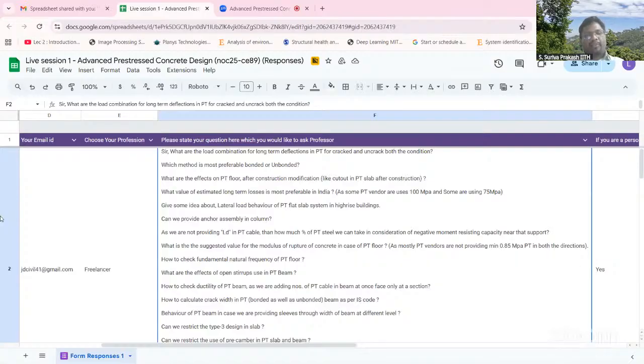So that's the reason FRP-based strengthening is typically very commonly done when you do the cutouts around the region, depending upon how much reinforcement you have lost. You calculate the equivalent amount of FRP required and you put it both top and bottom, depending upon your bending moment profile. Or you can go for an external PT. So these are the ways with which we can tackle this. But how much loss will happen, to be honest with you, I don't know. We have to look at the specialized literature. Maybe we'll look at it and come back if people have studied that.